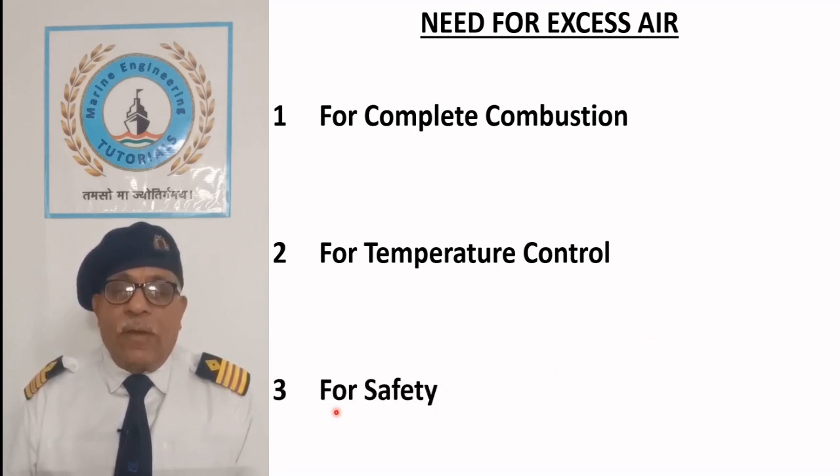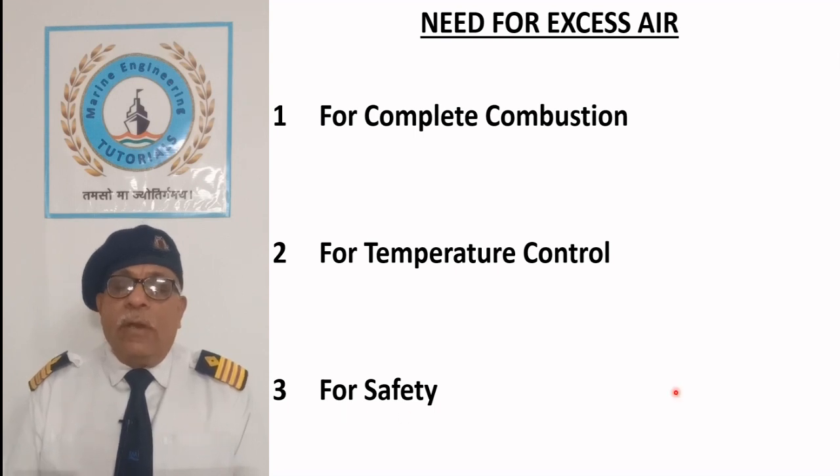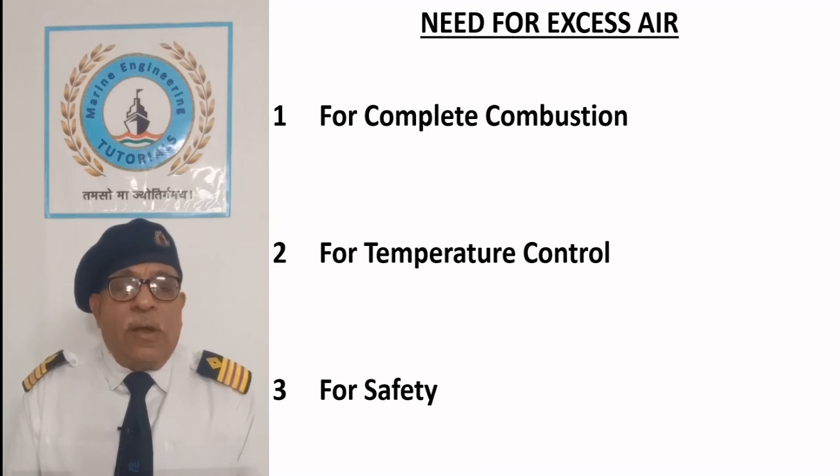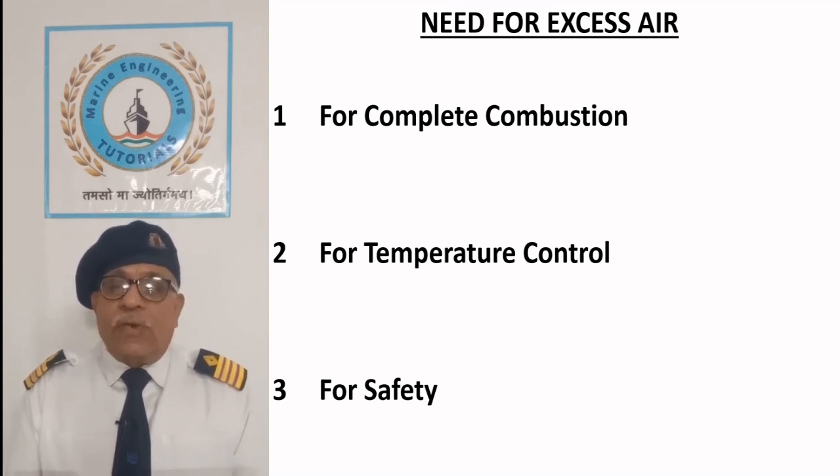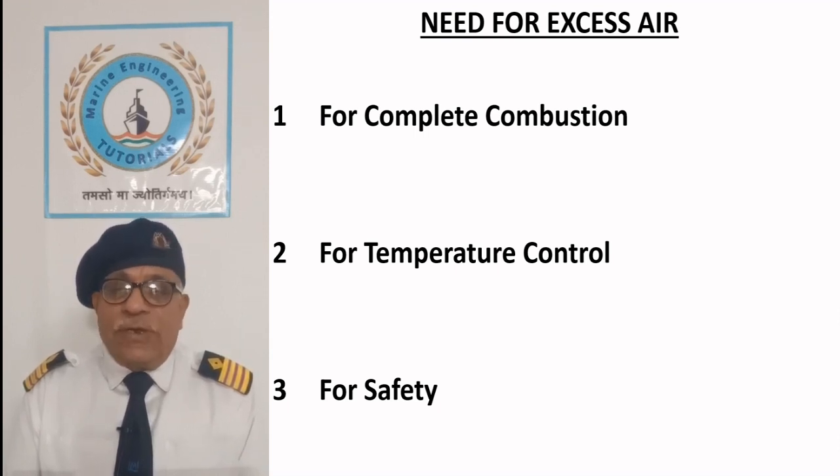For safety, maintaining an appropriate amount of excess air is essential for safety. Insufficient air supply can lead to incomplete combustion, resulting in the formation of carbon monoxide, a highly toxic gas. Excessive air, on the other hand, can lead to operational inefficiencies and energy losses.